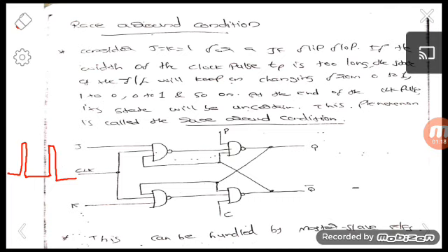So just take an example of a normal JK flip flop. This is the figure of a normal JK flip flop. Suppose J is equal to 1 and K is equal to 1 and our present output is 0, that is Q is 0 and Q bar is 1. For the better operation of this flip-flop, the width of the clock pulse should be too short. It should be just a peak-like structure. Then only the flip-flop will actually work.